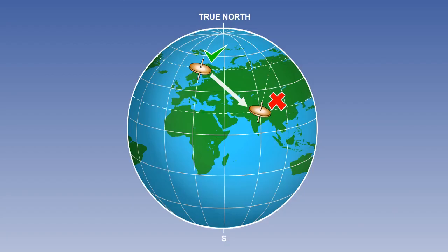It follows, therefore, that as the latitude nut is set for a specific latitude in a workshop and cannot be changed in the aircraft, it will be correct only at the latitude for which it has been set. This may not necessarily be the same latitude as the aircraft's actual latitude.